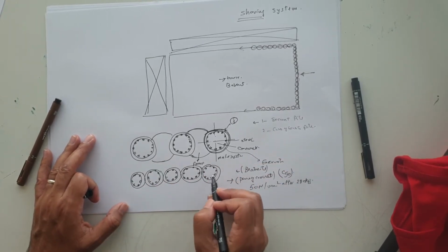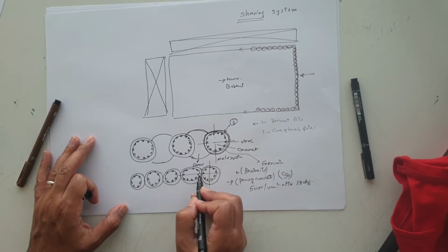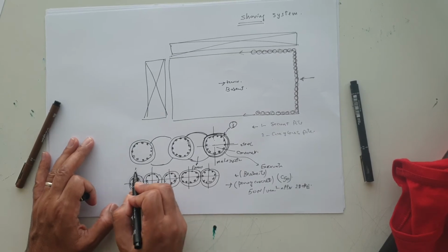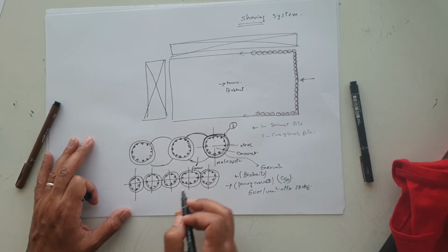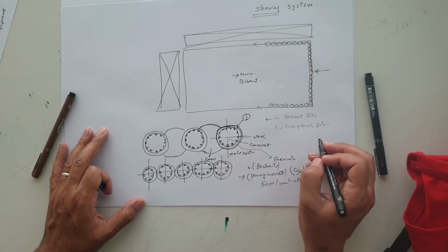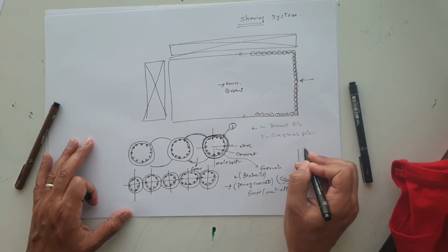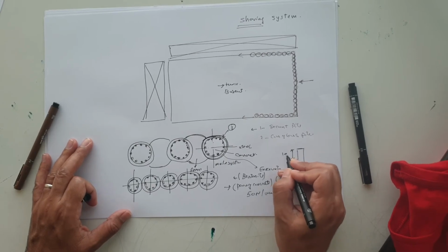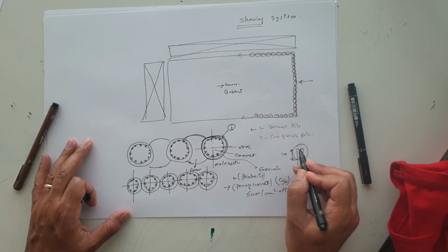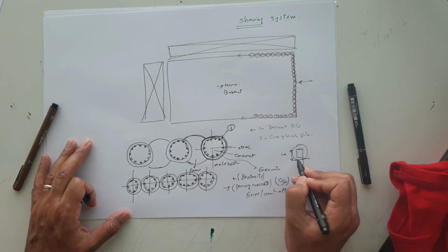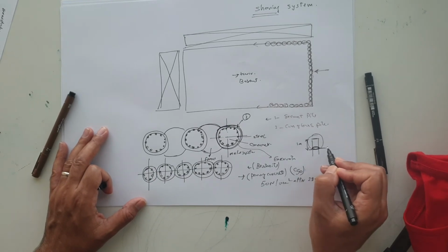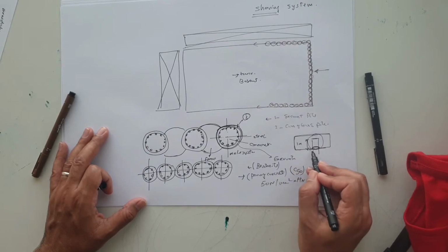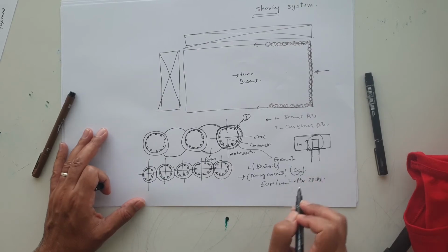Same procedure: we make excavation first, then we put the steel using the bentonite and cast the concrete. After we cast the concrete, we cast the pile concrete 1 meter more. Then we demolish this 1 meter and start repairing the surface of the pile to proceed for the pile cap as a next step after finalizing the pile.